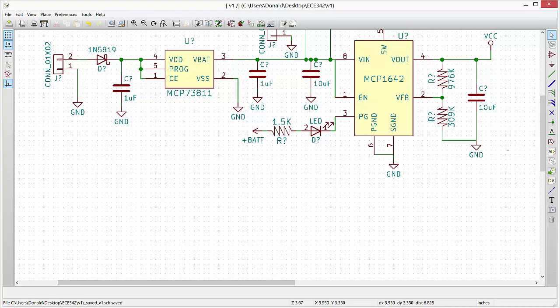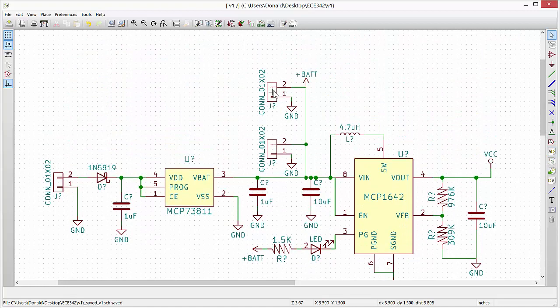So that's pretty useful also if I want to do things like rotate. For example here, if I want to rotate just that text, not the whole part, I'm highlighting over the text before I click something, which is the R key in this case to cause a rotate, and then the M to do a move. So that's dang useful to be able to actually adjust the thing that's directly underneath of your cursor at the time, allowing us to get a much cleaner design.